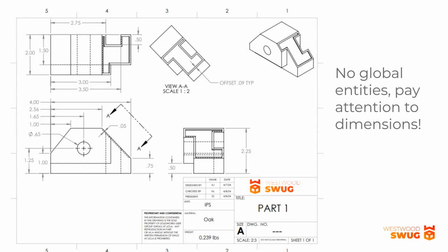And then for this you're going to do convert entities to that one, right? You want to convert, and then you're going to offset. So highlight them all, draw a box around them. And then offset. And then you want to flip it so it's in.